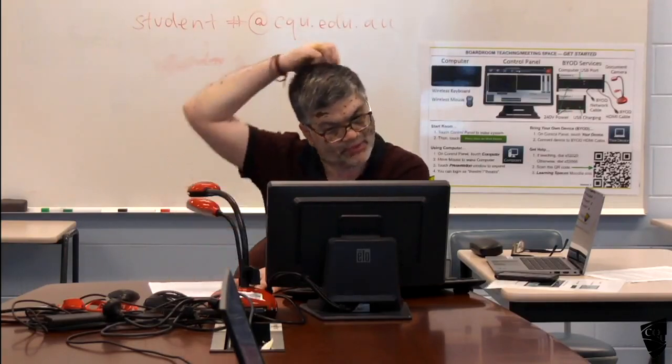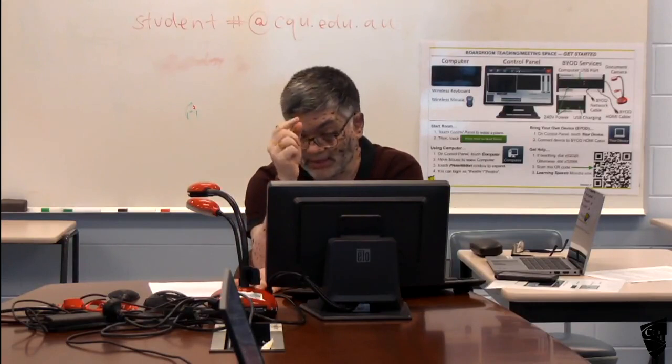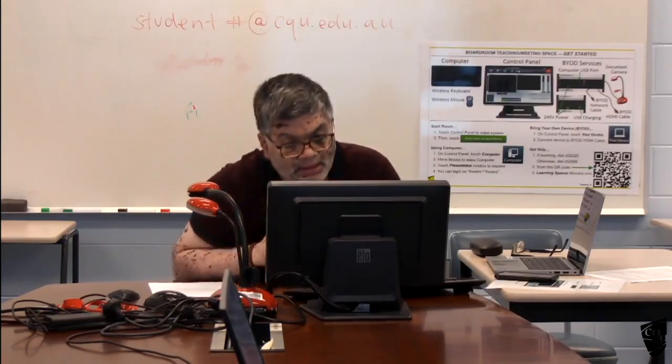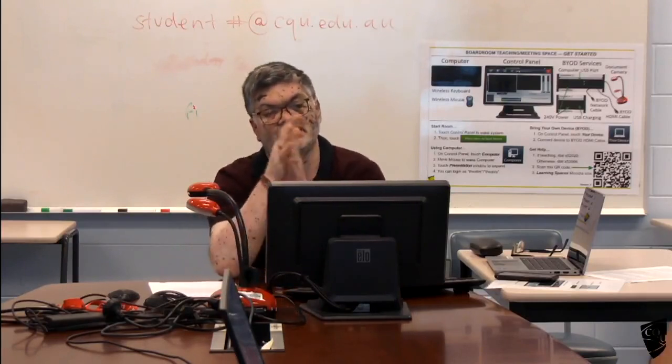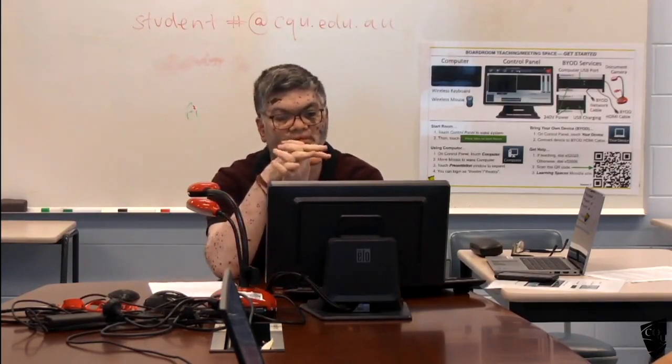We'll check for the crack control. The crack control calculations are same as we did in the beams. That's what we did in the tutorial 1. So we'll check that crack control. If it is interior slab, generally you don't need to do anything here. That spacing 300 or 2D should be sufficient.